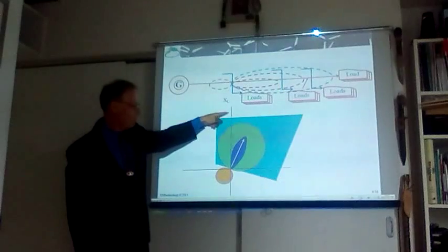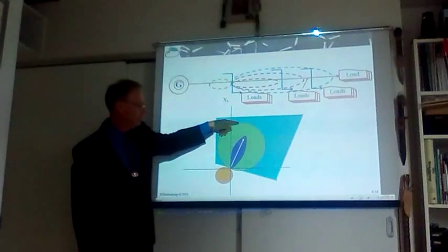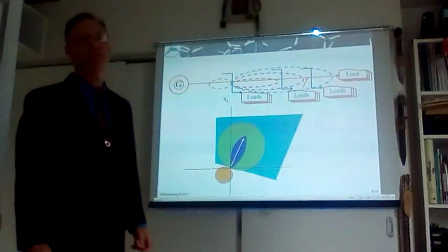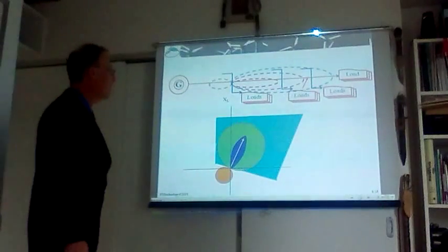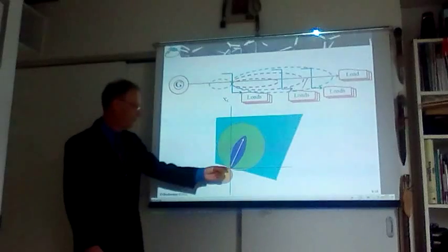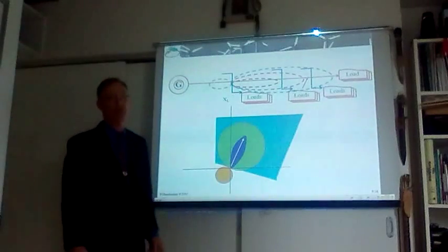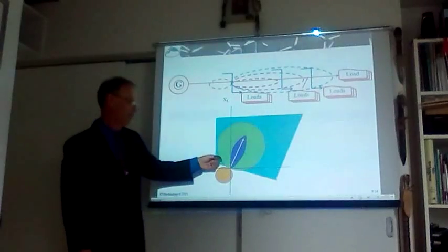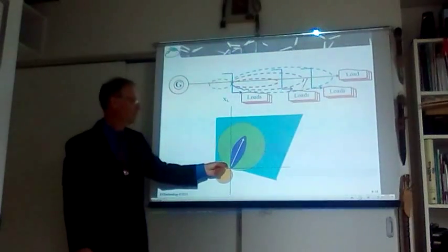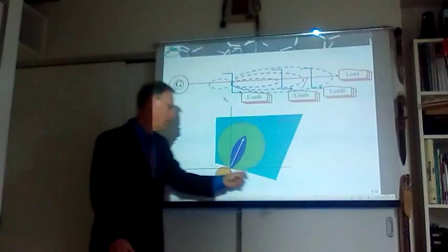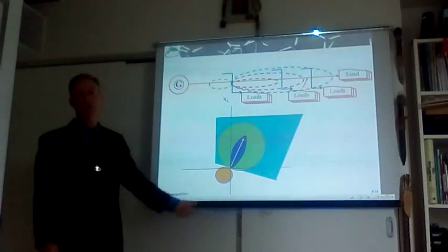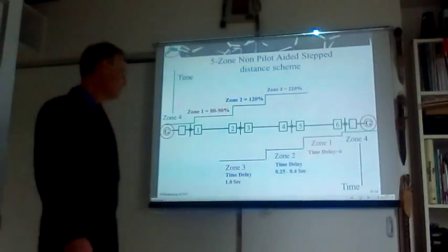If the impedance goes down, down, down, and it enters into that circle, that means that we have a fault. The zone of protection not necessarily will be described as a circle. It can be described as a circle, as a lens, as a rectangle of a certain shape, and of course, as we said, backwards.